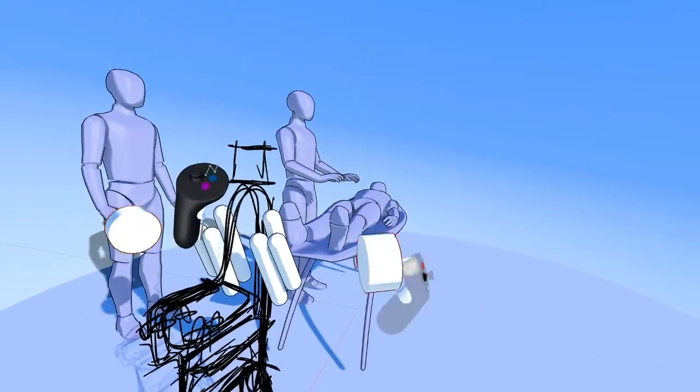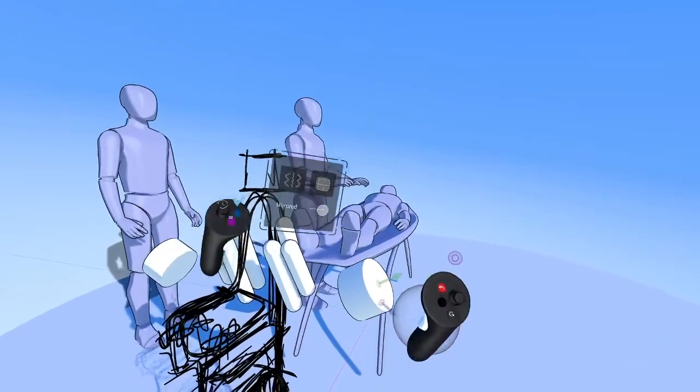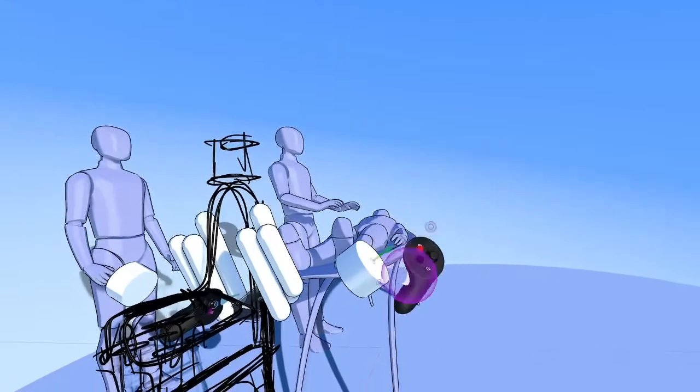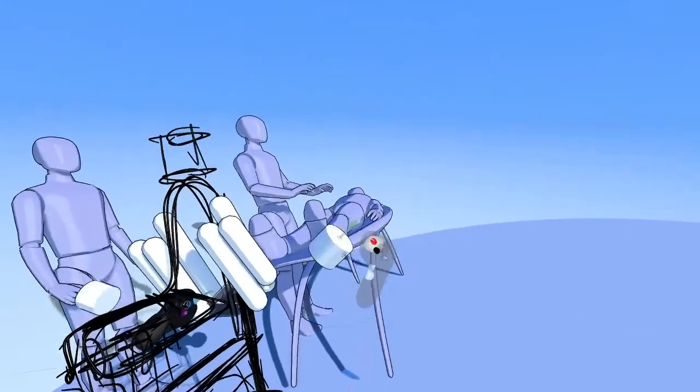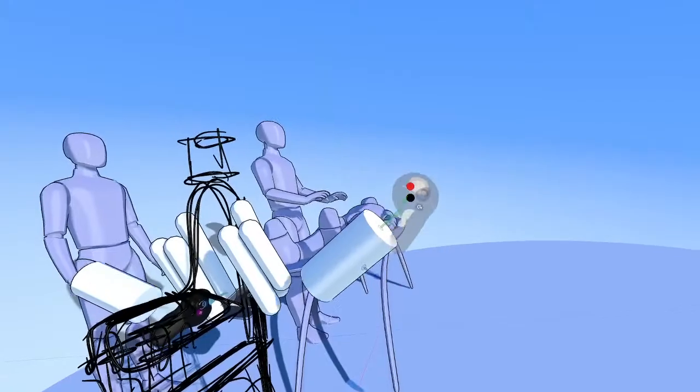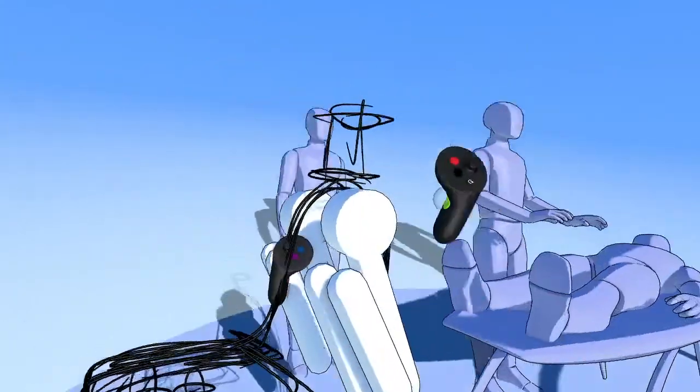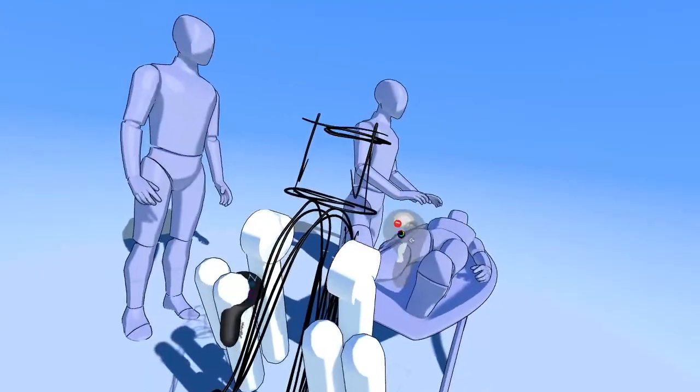And if you drop a primitive shape in and put it into edit mode, you get these very simple ways of adjusting the size and scale of it. So in this case for the cylinder, I just have two arrows, one for the radius, the other one for the depth of it. And that's all I want right now because we're just doing this very blocky thinking.